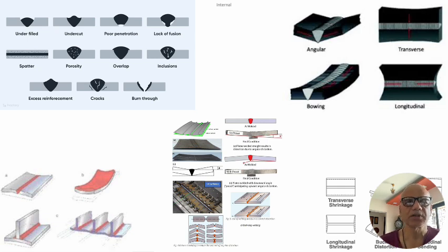The dye penetration test sometimes will reveal it, in case the root is penetrated and not everywhere it has fused. So visually you will not be able to see that, but the red dye will surely come out as you put the developer on the other side.